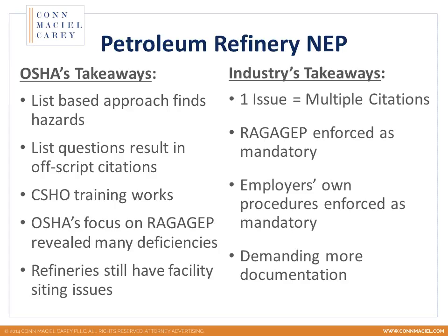And so when you develop those procedures, your mechanical integrity procedures, OSHA is then going to hold you to that and say, you've identified how you will meet the performance objective, and that procedure you've just introduced is now the law, and they will enforce it as mandatory. So if you're not complying with RAGAGEP in the previous bullet or your own internal programs, policies, or procedures, that's going to be a violation of the PSM standard.